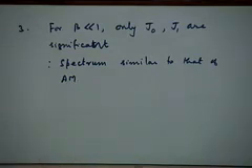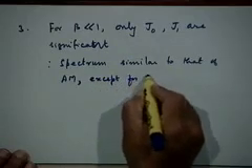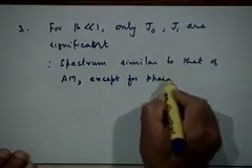While it is similar, it is also slightly different. In what way is it different? That's right. The two sidebands are phase reversed with respect to each other. There is the negative sign of one with respect to the other, right. Fc plus Fm has some amplitude and Fc minus Fm has a negative amplitude, which means it is phase shifted by 180 degrees, right. So except for the phase reversal of the lower sideband component.